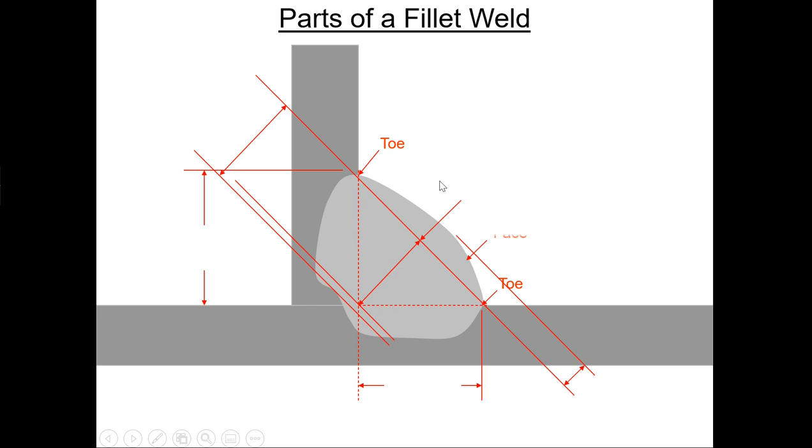So the toes represent the important part of the face, the front of the weld, and the face, of course, we're looking at for the shape. We're looking at the face for signs of porosity, cracking, anything like that. It's quite common that you will see cracks that will start to develop and maybe pass back a little bit in this direction, right? You can actually see the crack in there. Make sure you speak to your supervisors or team leaders if you start seeing any cracks that go into base metal. I'll tell you right now that they're going to take that very seriously.